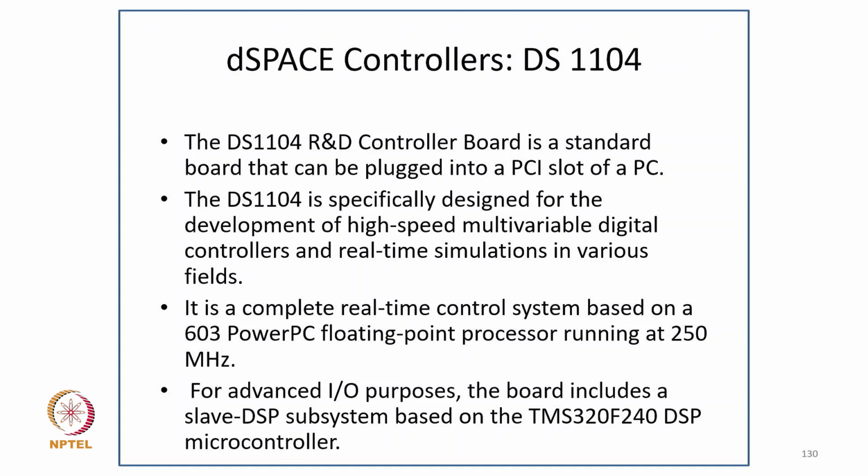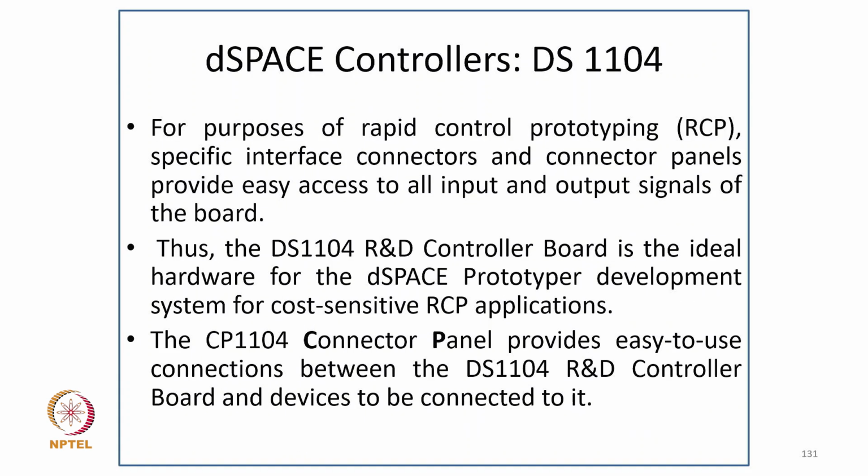It is a complete real-time control system based on a 603 PowerPC floating-point processor running at 250 MHz. And for advanced input-output purposes, the board includes a slave DSP subsystem based on the TMS320F240 DSP microcontroller. For the purpose of rapid control prototyping, specific interface connectors and connector panels provide easy access to all input-output signals of the board, and thus the